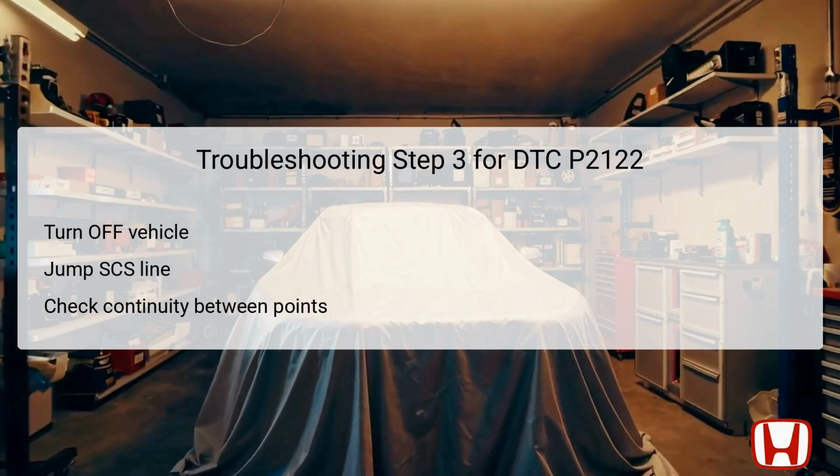In the third step, turn the vehicle off and proceed to set up for continuity testing. This involves jumping the SCS line using the HDS. This SCS short will help ensure that you are in a mode suitable for diagnosing issues.